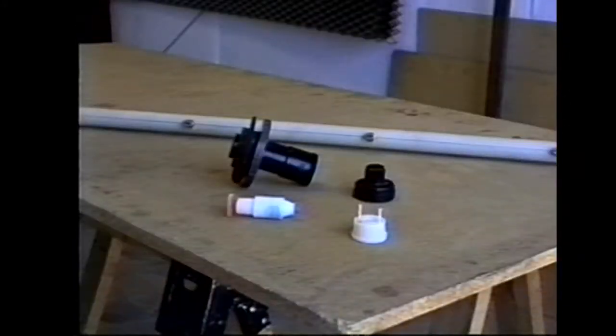There are several ways to power the spray wands. Here are the parts for a spray wand which uses a gear-operated sprinkler as a drive unit. Some of the pressurized water from the booster is used to drive these sprinkler-based units and the recycling venturi. Another rotation mechanism uses a turbo drive, which uses a small jet of water to turn some paddles. The rotating paddles then turn a shaft, which turns the wands inside the tank.